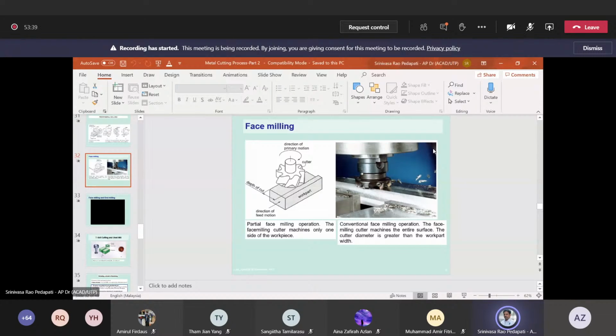So in the case of end milling, if you see, it is also, Mr. Che is mentioning here, end milling is like smoothening the surface. It is not smoothening the surface. It is making the hole. It is removing the material, but it is removing the material with the help of both face and side. So that is an end milling cutter.